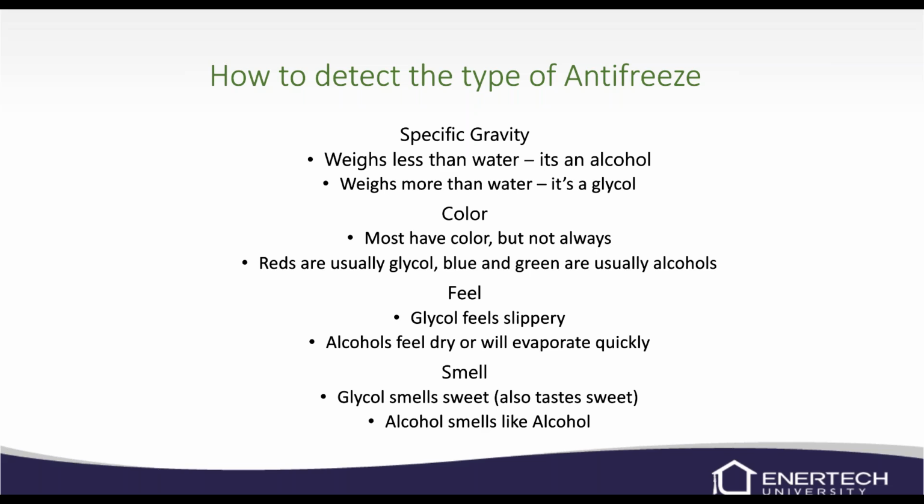So if you put a glycol hydrometer into water that has alcohol in it, it's going to sink to the bottom almost immediately. If you put a methanol hydrometer into glycol, it's just going to float at the very top.